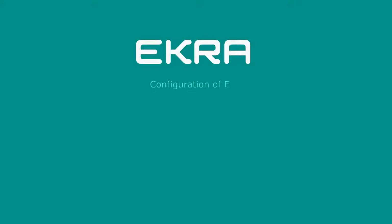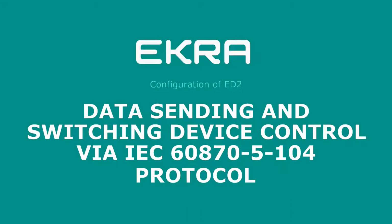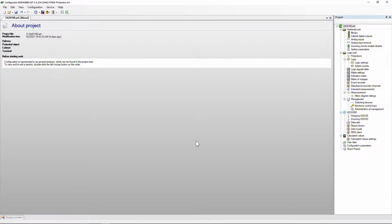In this video tutorial you will learn how to set data transmission and switching devices control via IEC 60870-5-104 protocol. Next, we will consider setting the protocol in the Configurator software. Similar settings can be made in the Smart Monitor software. Before starting to work with the configuration, it is recommended that you watch the video tutorial configuration opening and saving.